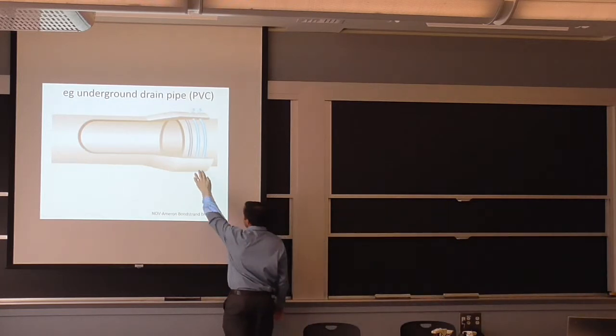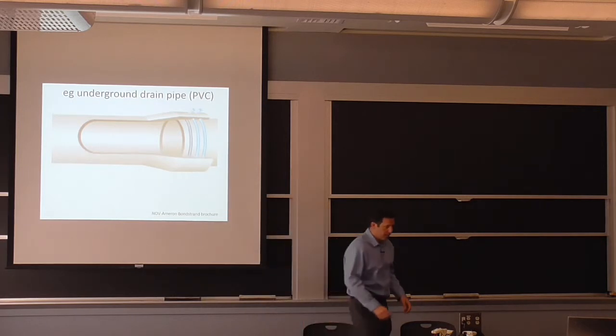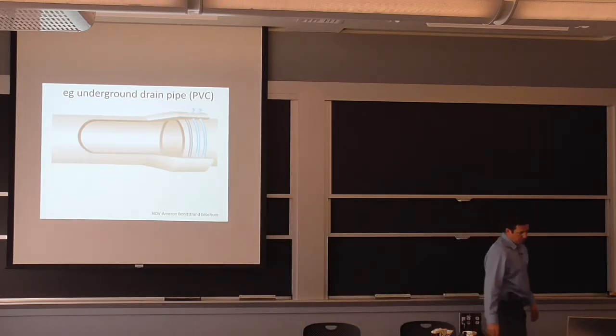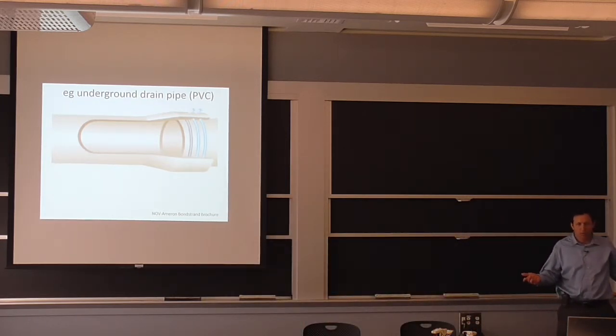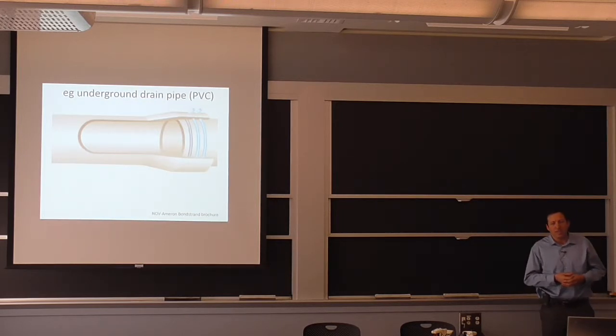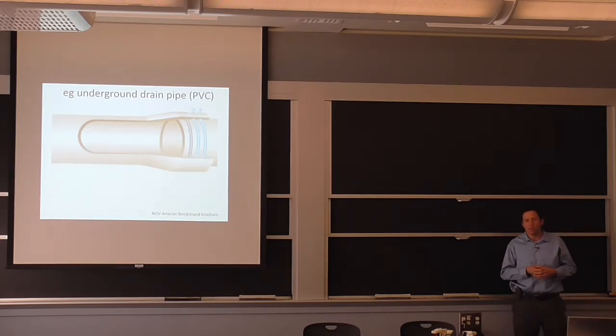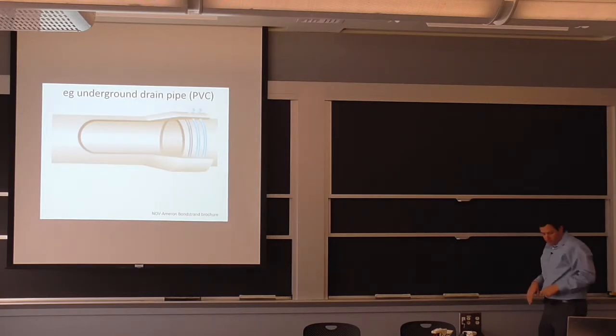Because one disadvantage of the plastic over the metal is when you have temperature variation, you have more changes in length. So the thermal expansion coefficient can be about 4, 5, 8 times more with the plastic than the metals. It has implication if you're looking at a system that has bends, which is most building plumbing systems.